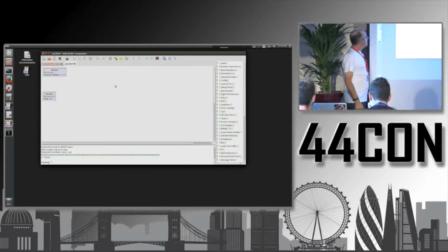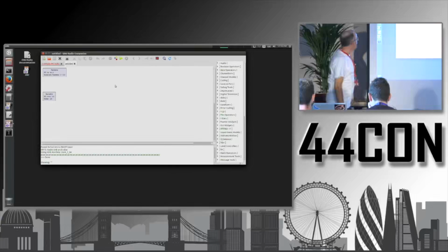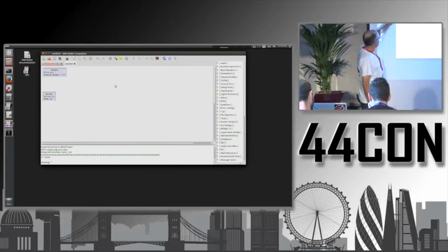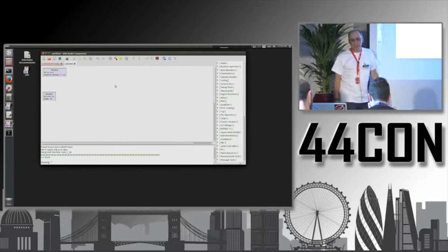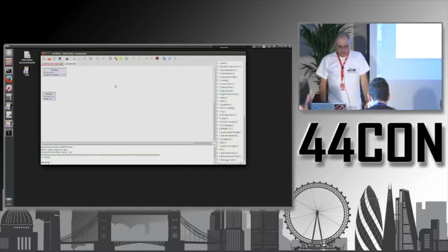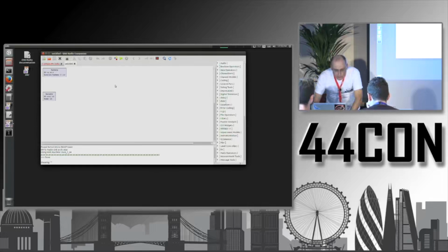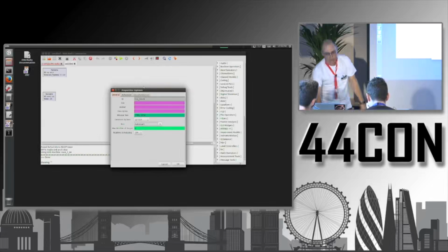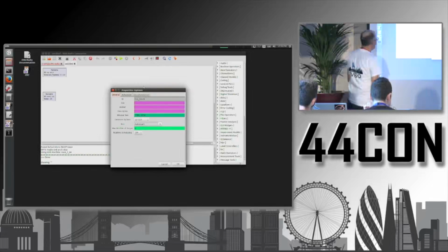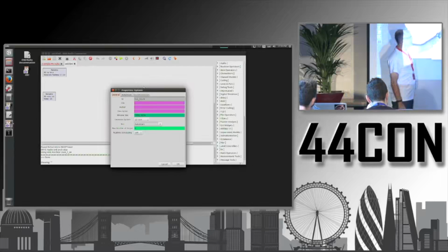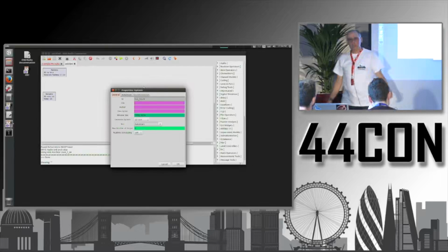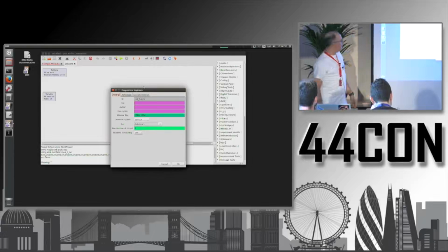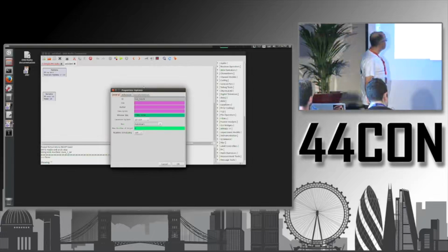And when you do that, only two blocks are generated for you. Okay? One with the options and one with a variable. Okay? We are going to change the options, so you can double click options. You see here the ID is top block. That's why the Python program was named top block, because it's the ID of the options.